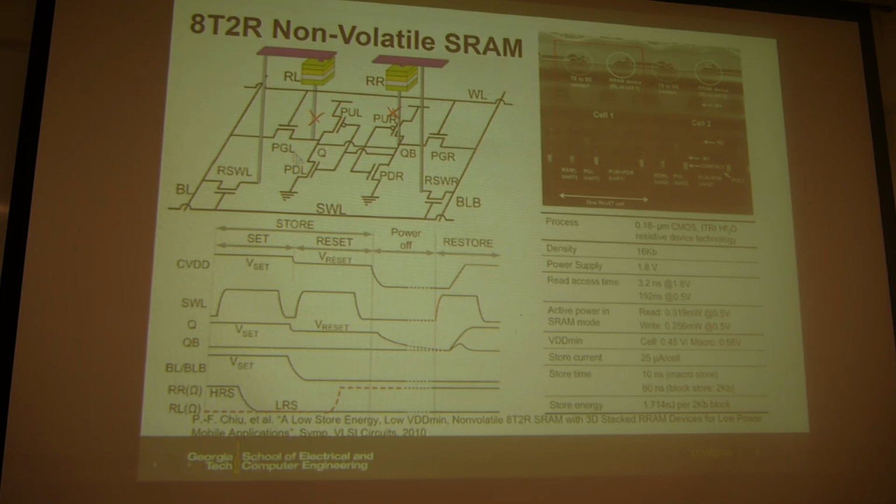So this is just the regular 6T SRAM cell operation. You have the read and write operation to the SRAM cell. Maybe the speed will be affected a little bit because of the additional capacitance due to that contact wire, but overall it's the same function as before. So you do the regular read and write to your SRAM cell.